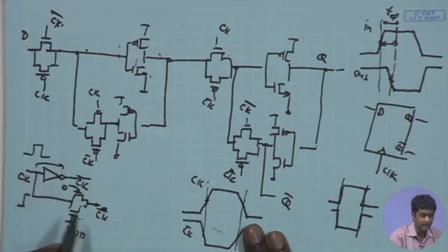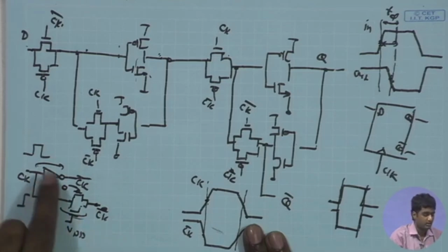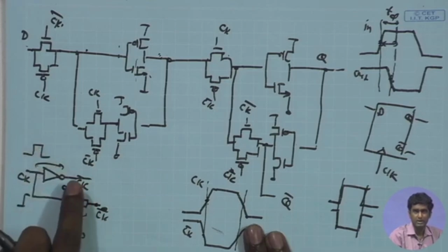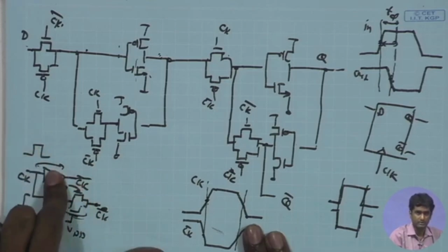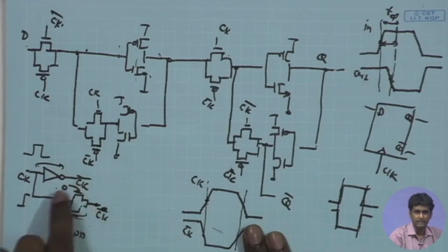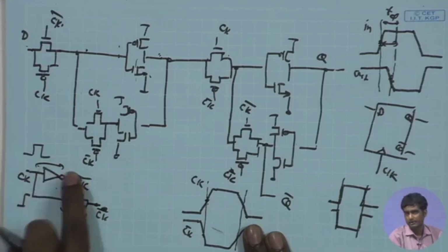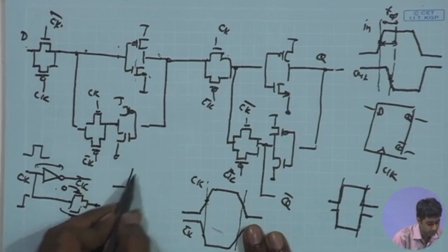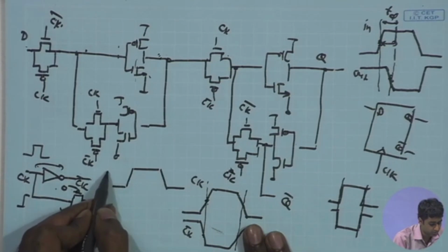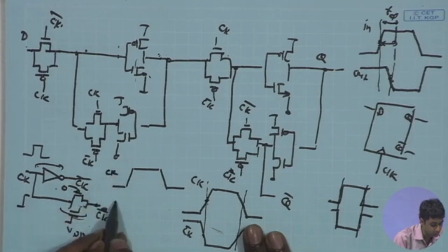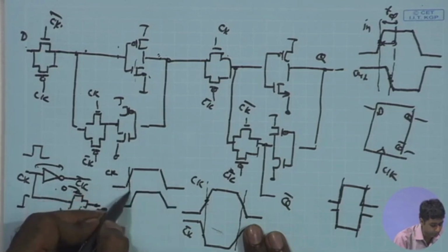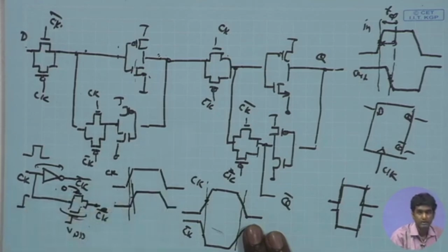The inverter has its delay TD, likewise the transmission gate will have some delay TD, and to some extent these two delays can be matched, not exactly, if you size them properly, with the NMOS and PMOS having similar dimensions. The TG output, if this is the CK input waveform, will be just the same waveform, but delayed by a small amount given by the distance between the midpoints.